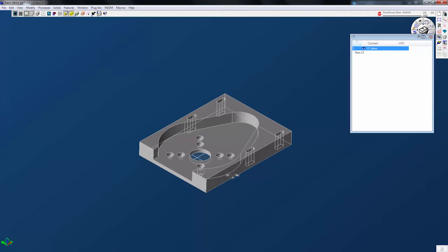So I'm going to go ahead and make a new coordinate system. Now that new coordinate system is overlaying on the old one, so you can't really see it. So I want to move it to this corner point. I'm going to extract edges. Let's do it. So there's that point. So I'm going to modify it. Let's pull up my modification palette. And I want to move it to a point.